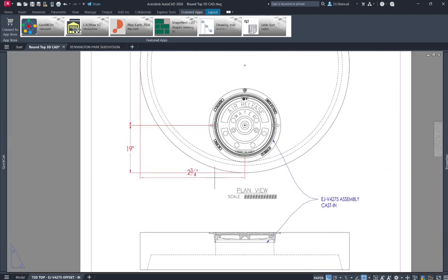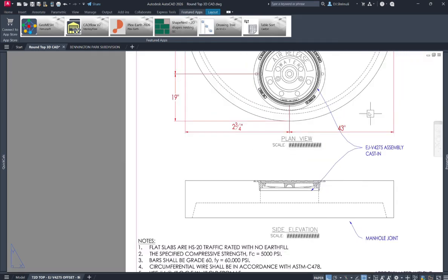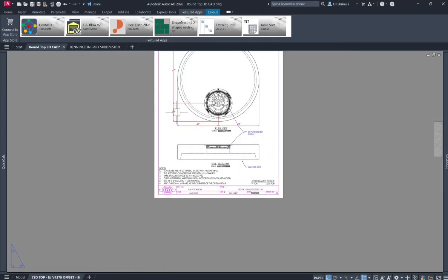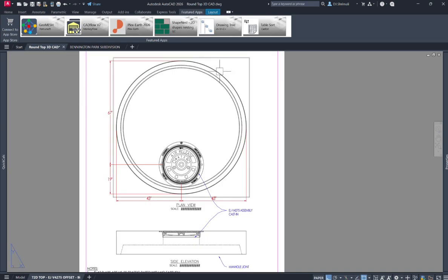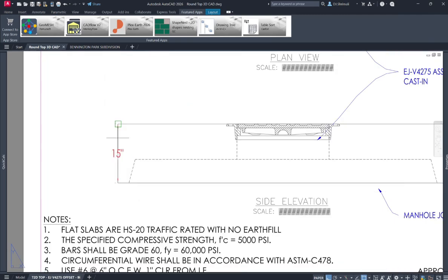But you see 19 inches, that's the actual dimension of that length. For round openings we always dimension to the center location. The 4.5 inches that was showing earlier was because it was taking the paper scale dimension. But when you draw the actual dimension or select the proper lines, just like that 15 inches, it will give you the proper dimension.